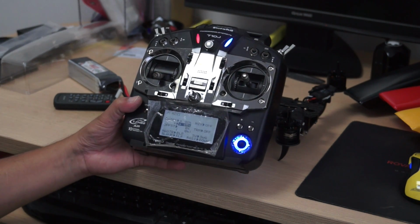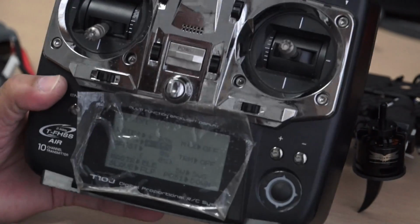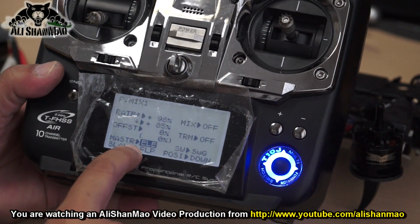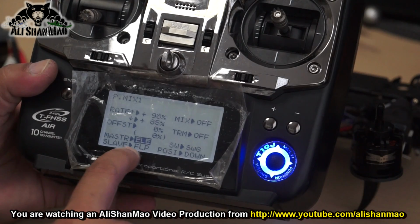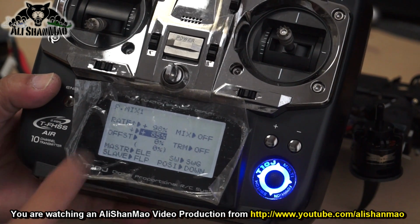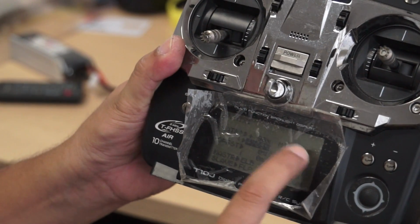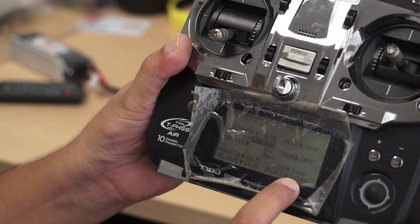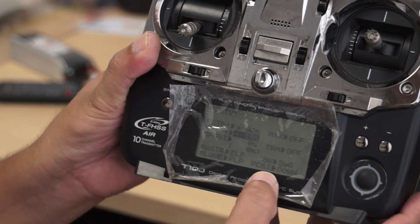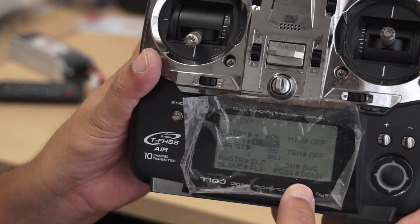My channel 6 is flaps. Let me zoom in. My channel 6 is flaps. So I have created a mix. Master is the elevator and slave channel is flap, that is channel 6. And then I go ahead and put in the values according to how much my motors will tilt. Next, you will have to set a switch. In my case, I have set switch G, right here, and the position is down to turn on this mixing.